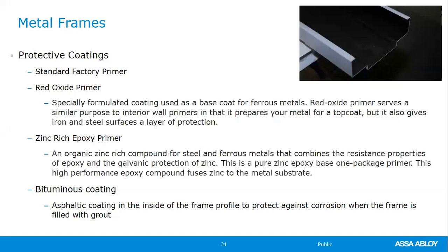Over the last 7, 8, 9 years, the industry has come out with a water-based, environmentally friendly bituminous coating. It can be used on fire-rated or non-rated frames, 3-sided frames, bar lights, side lights, welded KD. If you have a shop, your shop guy can actually put this material in the back of the frame to coat it.